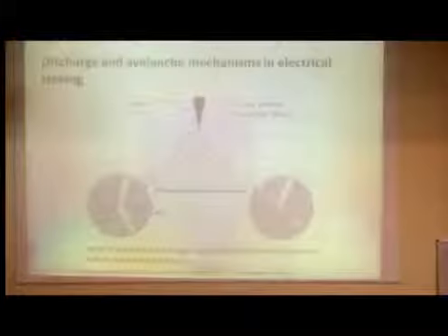What about electrical treeing then? What would we expect to occur there for a start? Well, electrical treeing probably has two mechanisms going on. One is that inside these tubes we'd expect to have electrical discharges. And we know that because we can see it. We can see light being emitted from the electrical trees.